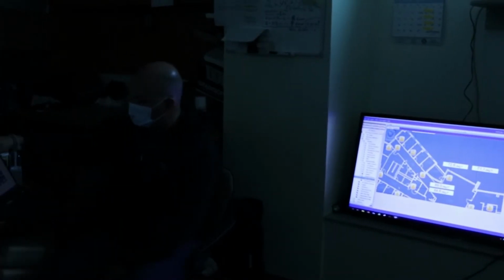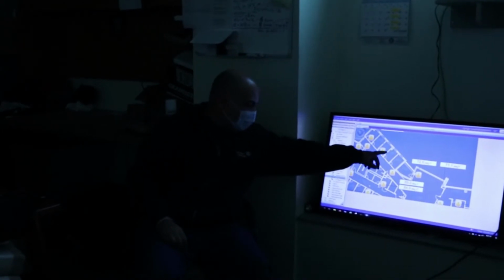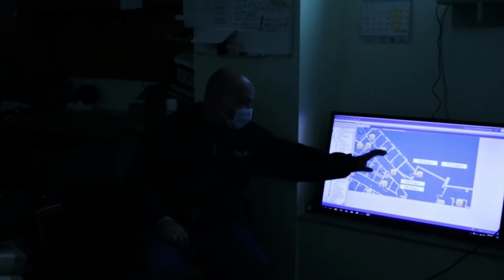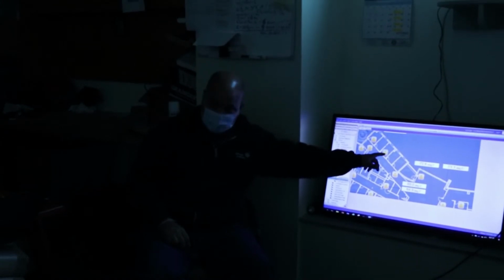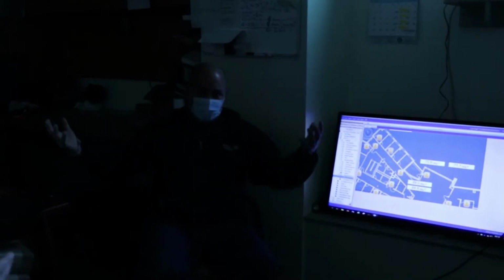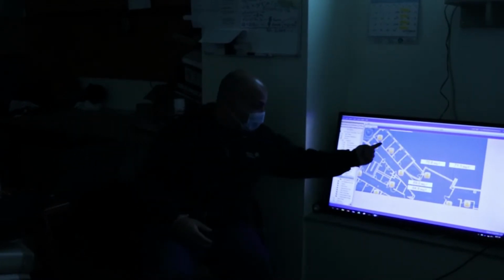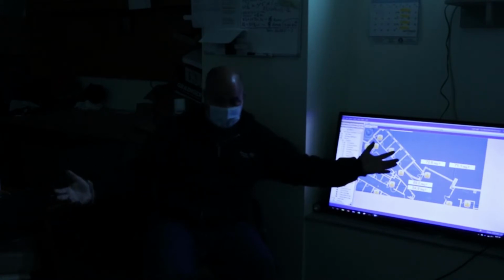Right, so we have these three rooms, 12 and 11. One VAV box feeds these three rooms. I can tell you that the room the sensor is in is going to determine how much air the VAV lets in. You know how VAV works, it lets more or less air. The air coming out of the outlets is all going to be the same temperature.